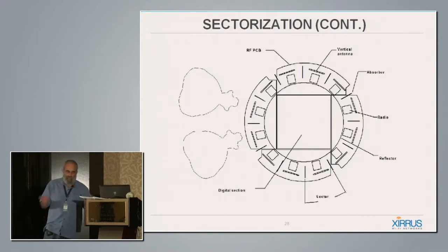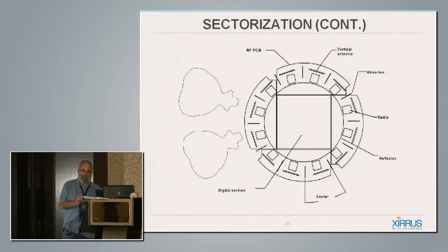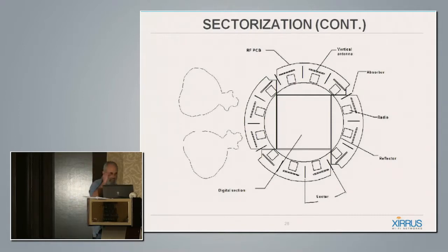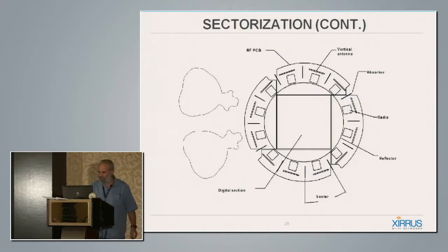If you take that 40 dB and you add to it channel selectivity, and there are certain things you can do in the software part, and you can control the power at the ends of the link, you're able to achieve a situation where the radios are working in peace with each other within the same box, and achieve as good capacity as can be done compared to a mesh network deployment.